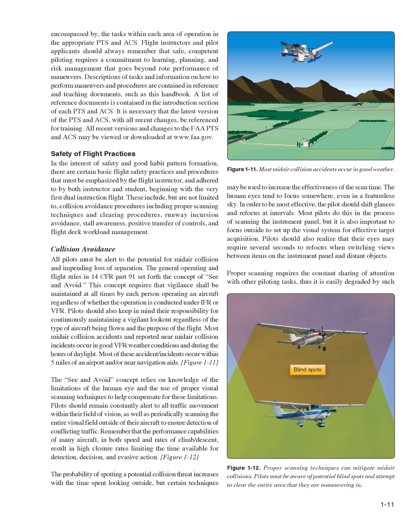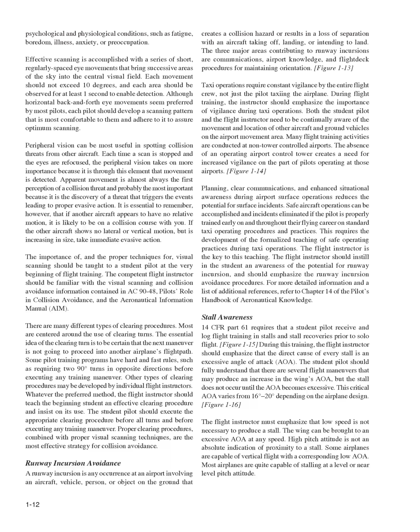Pilots should also realize that their eyes may require several seconds to refocus when switching views between items on the instrument panel and distant objects. Proper scanning requires the constant sharing of attention with other piloting tasks, thus it is easily degraded by such psychological and physiological conditions, such as fatigue, boredom, illness, anxiety, or preoccupation.